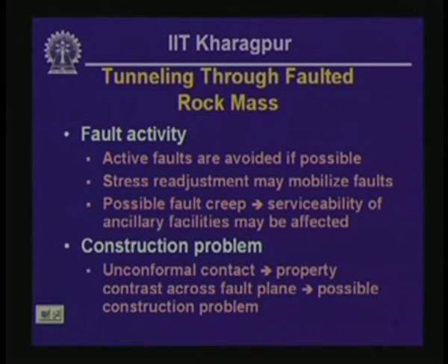So, this fault movement can actually generate earthquakes, and those earthquakes are so near to the mine's operation that they are quite hazardous from the point of view of the safety of the tunnels. So, mine induced seismicity is a big problem of tunnel stability in case of deep underground mines operating in hard rock areas. Now, you also have to account for possible fault creep.